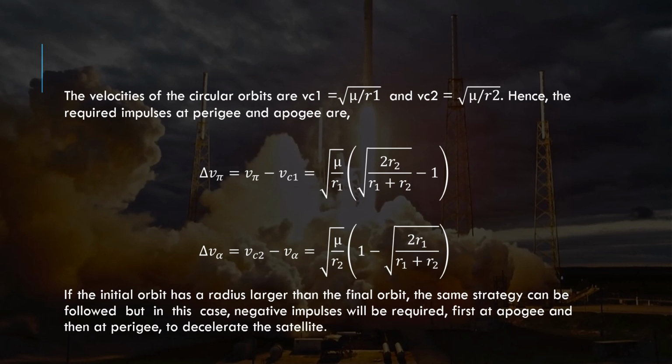But there is one condition which is important to note in this method. If the initial orbit has a radius larger than the final orbit, then the same strategy can be followed, but this time a negative impulse is produced. As a result, the rocket will decelerate, that is, its speed will decrease.